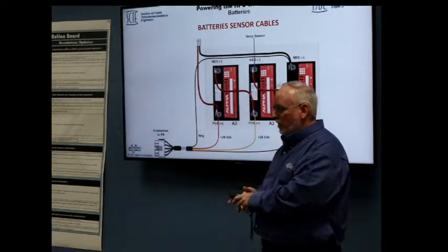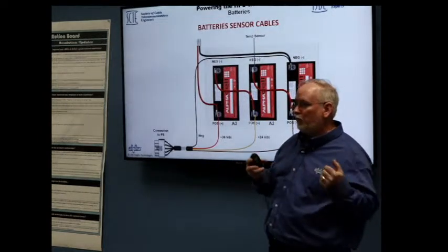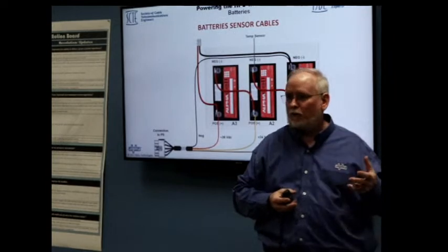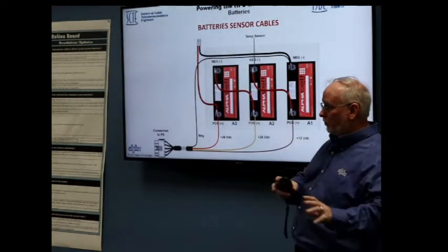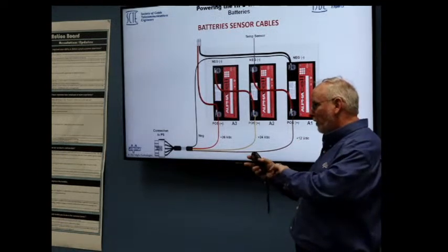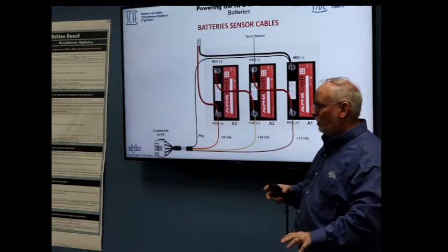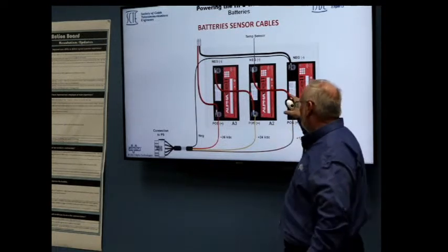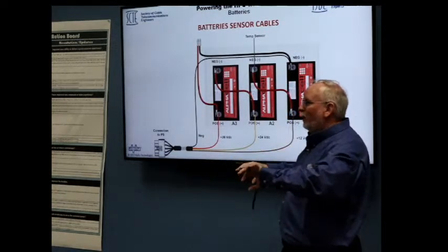Now, why do we need this? In order to charge a lead-acid battery, there is a temperature variant. It's 5 millivolts per degree C per cell. It's the standard lead-acid. It can be as small as 0.2, as much as 0.5. But what that does is, as the temperature gets colder, I have to jack the voltage up on the charger to get any electrons to flow into the battery. In other words, it's hard to move those things through that cold liquid.